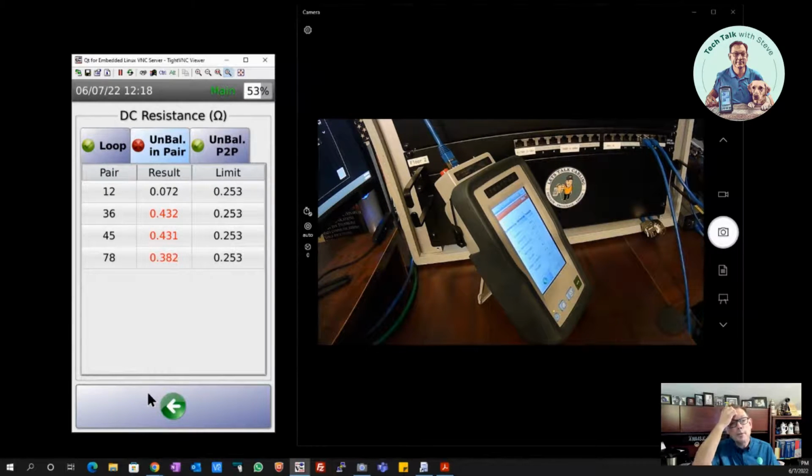And what happens is if you have some unbalance issues with your cabling and you're trying to run PoE over it, the power needs to be very well balanced going from the source out to the device. If you get some unbalance, what starts to happen is you get some issues with the PSE, you get some issues with the power device, and not just that they're not working, but you can start to see some actual troubles in the PSE.